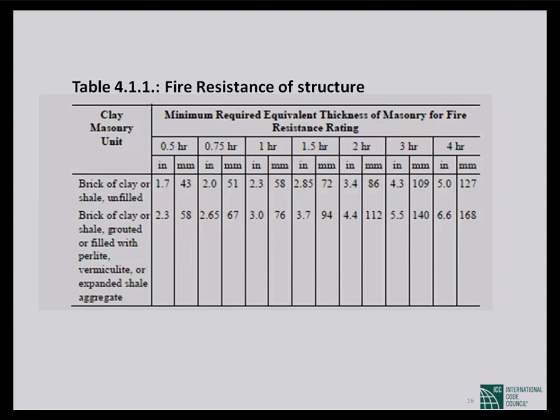In Bangladesh, more than 99% we use solid brick. Now we are gradually moving to hollow brick or unfilled product, but at this moment, we are mostly with the solid brick. Unfortunately, solid brick data is absent from this BNBC. So for that, you have to go to ASCE 29 again.